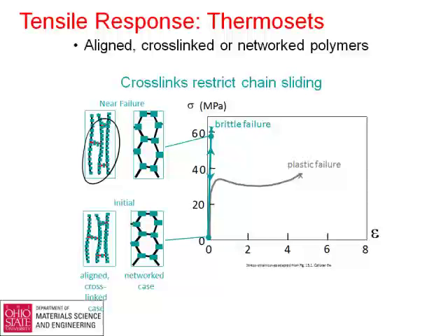So if you've got something that is fairly highly cross-linked like this, it will fail fairly brittly. If something is not as densely cross-linked, you can see the same sort of thing, but again, typically not the same kind of elongation you'll see in a thermoplastic polymer. And again, if you were to take this material, stop the test here, heat it back up again, it will probably shrink back down for you.